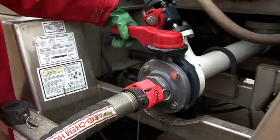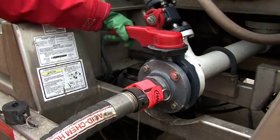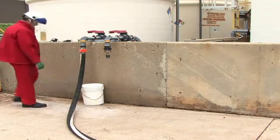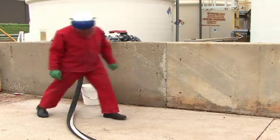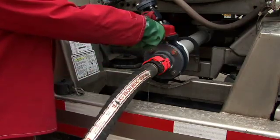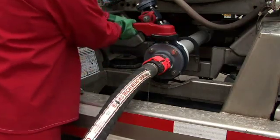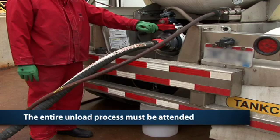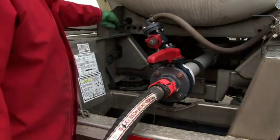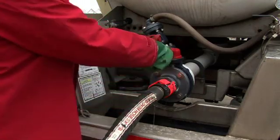Inspect all valves for proper position, then slowly open the unloading valve on the shipping container. Once the transfer has started, inspect all transfer lines and connections for leaks. If a leak is detected, stop the transfer and correct the problem. DOT and Transport Canada regulations require that the entire unloading process be attended. Once the transfer has been completed, shut off the air supply or pump and close the unloading valve.